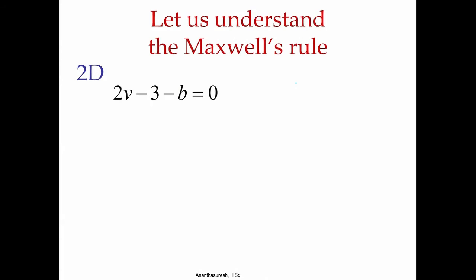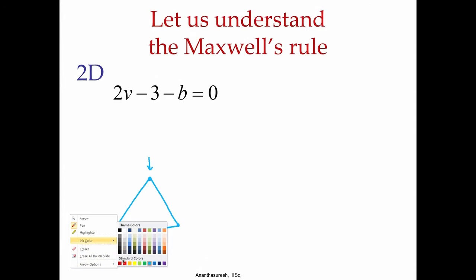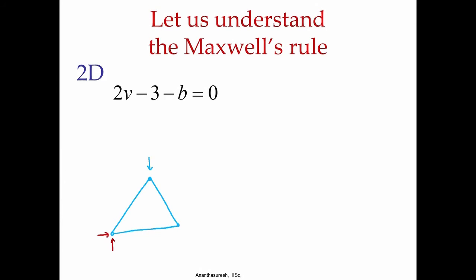It comes about because whenever you have, let us say I take a truss such as this, and there are some forces acting, and there could also be the ground reactions as we call. Let us say this one has a pin joint to the ground, let us say third link is fixed. So, we have that, and if it is sliding, there will be only vertical reactions, we can freely slide in this direction, what we call simply supported condition. If you put that and draw the free body diagram for this truss, at each vertex there will be the bar forces. Okay, let us say we assume that all bars are in tension. Let us call this F1, and hence it is F1, F2, F2, F3, F3, and those will come onto these vertices also in opposite directions at this vertex, and I have these ground reactions.